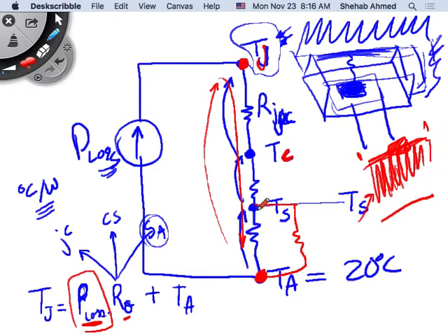So this sink to ambient, you have a lot of control over, right? So typically it's a large number if you have a poor heat sinking method, or if you're not heat sinking at all, right? And then anytime you do something there on the heatsink design, you add a resistance in parallel. Okay? If you add a cooling system, it's resembled as a resistance in parallel because it's going to improve the thermal resistance from your sink to ambient.